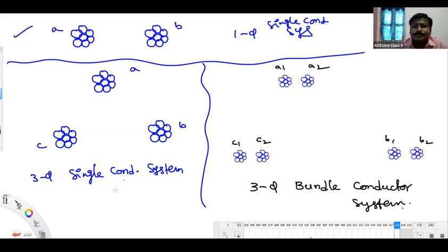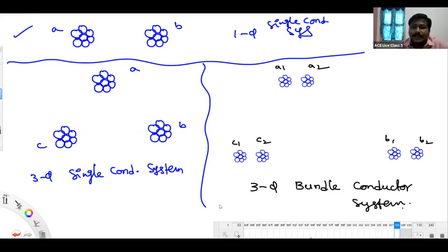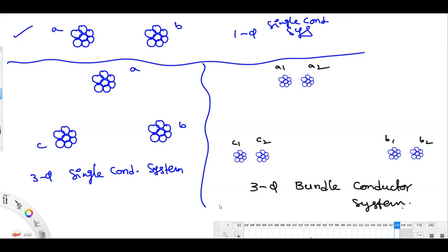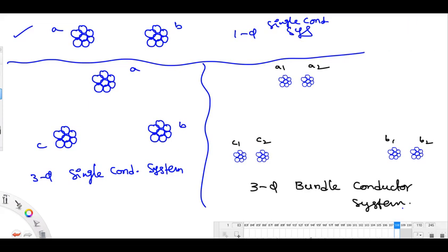Bhaskar: How do we calculate GMR for an ACSR conductor, sir? You have to follow the same procedure, Bhaskar, but you should consider a number of self distances. It's laborious, because of non-uniform current distribution. You neglect the steel wire.